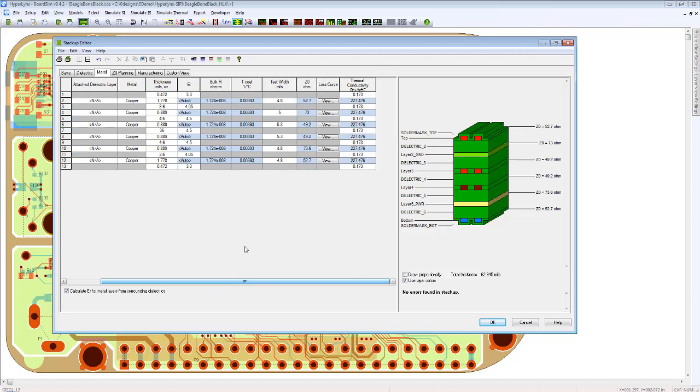And what we can do is make some cross-verification of the impedances. I looked at the PCB layout data and saw that the DDR3 address lines are routed on the bottom layer with trace widths of 4.8 mil, and are routed in the inner layer 3 using a trace width of 5.3 mils. Following this stack-up and the material parameters we gave, our address lines would have impedances of about 43 ohms on the outer layers and about 49 ohms on the inner layers.